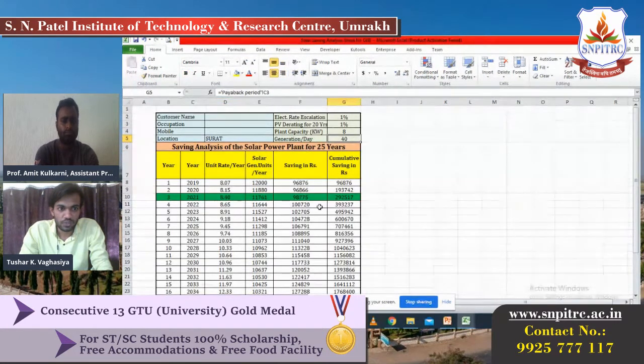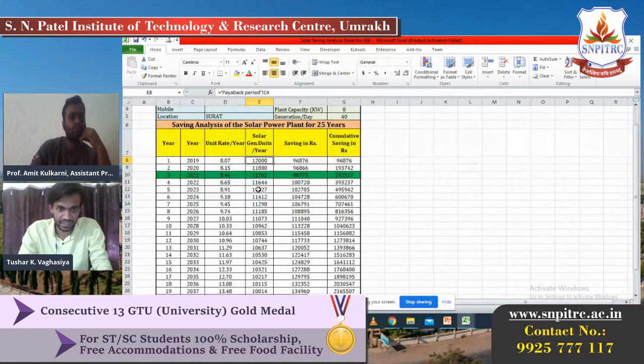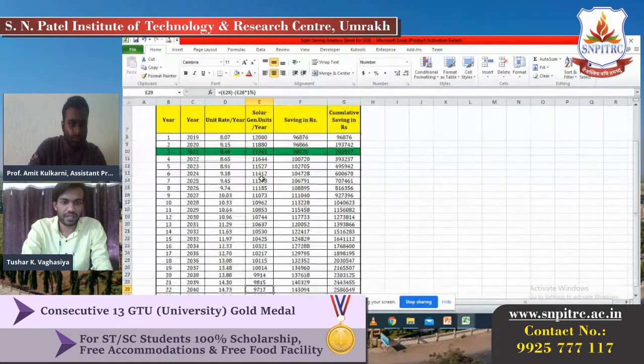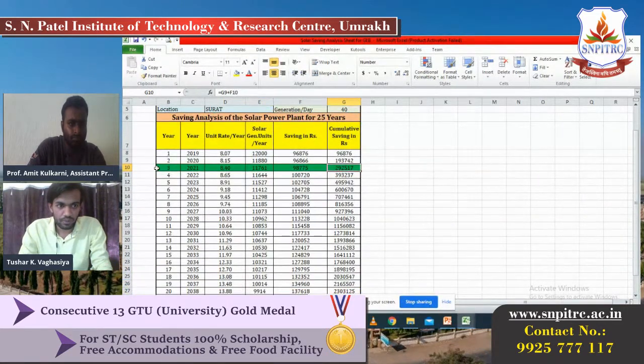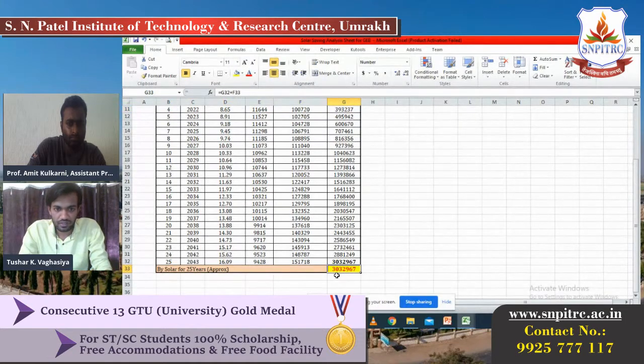Let me show you, solar power generation is not continuously at high efficiency. It will decrease by 1% degradation each and every year. So here we are taking the degradation, you can also say deceleration, 1% degradation each and every year, right? So if your generation in the first year is, suppose, 12,000 units during the year, in the second year it will be maybe 11,880, right? So here the 1% degradation is taken for each and every year, right? So you will recover your investment within 3 to 4 years, right?